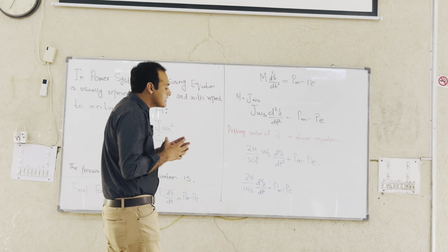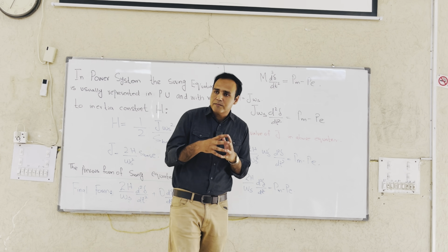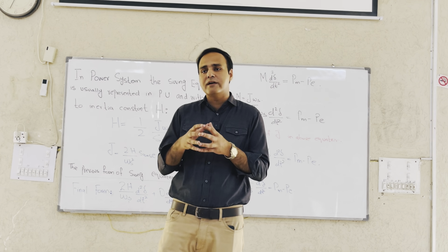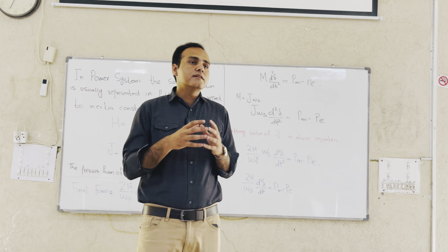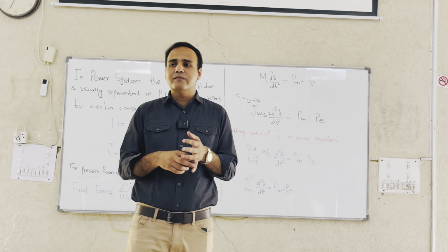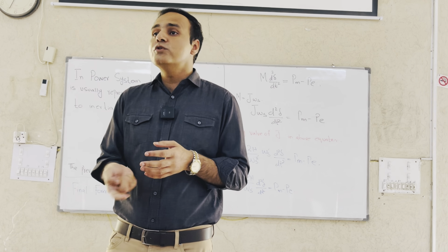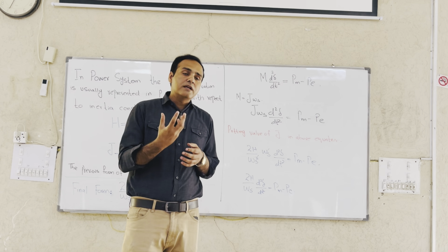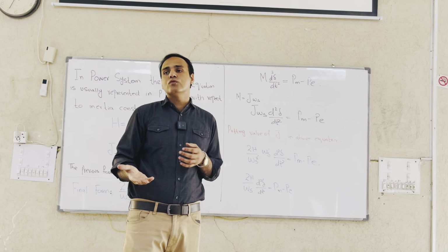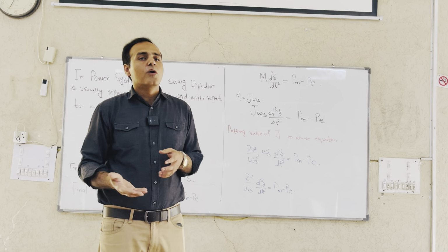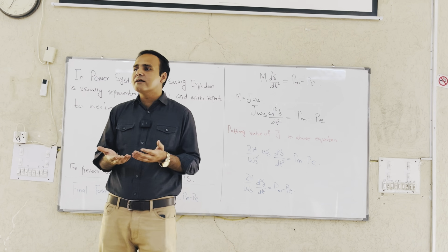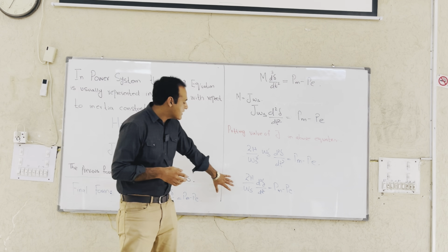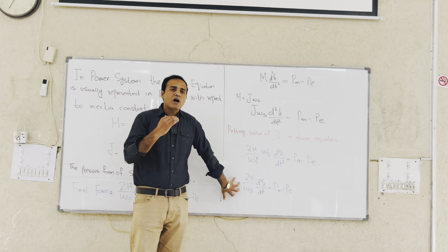तो फिर हमें इस वजह से अपने सिंक्रोनस जनरेटर के अंदर डैम्पिंग को रखना पड़ता है, और उस डैम्पिंग को रखने के लिए हम जनरेटर के अंदर एक वाइंडिंग रखते हैं, उस वाइंडिंग को हम कहते हैं डैम्पिंग वाइंडिंग। सही है। तो सिंक्रोनस जनरेटर में एक तो फील्ड वाइंडिंग, एक आर्मेचर वाइंडिंग, और एक और वाइंडिंग होती है जिसको हम कहते हैं डैम्पर वाइंडिंग। वो जो डैम्पर वाइंडिंग होती है, बेसिकली वो बनाती है डैम्पिंग इफेक्ट, और वो डैम्पिंग इफेक्ट अपोज करता है किसी भी डिस्टर्बेंस को जो आपके सिस्टम के अंदर आती है, और उस अपोजिशन की वजह से आपका जनरेटर दोबारा रीगेन कर लेता है अपनी स्टेडी स्टेट या सिंक्रोनिज्म।